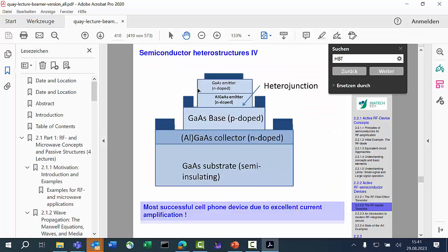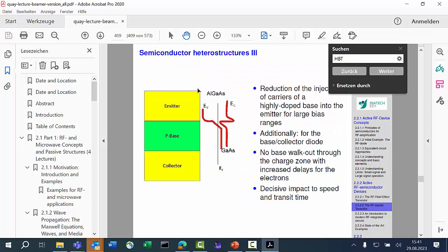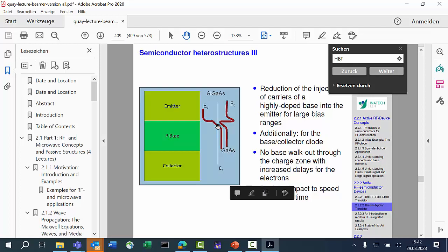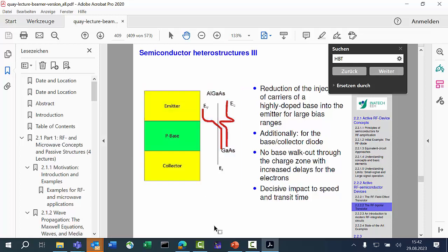And then we use this principle again here, that instead of just putting one material and dope it, we put again a high bandgap, low bandgap combination. And this is good because now this is the situation which we explained earlier. So the electrons can still travel because they can tunnel. That's no problem. They can go in there. But in the energy scale, this is now important. When a hole is energized, it goes down. Yeah?